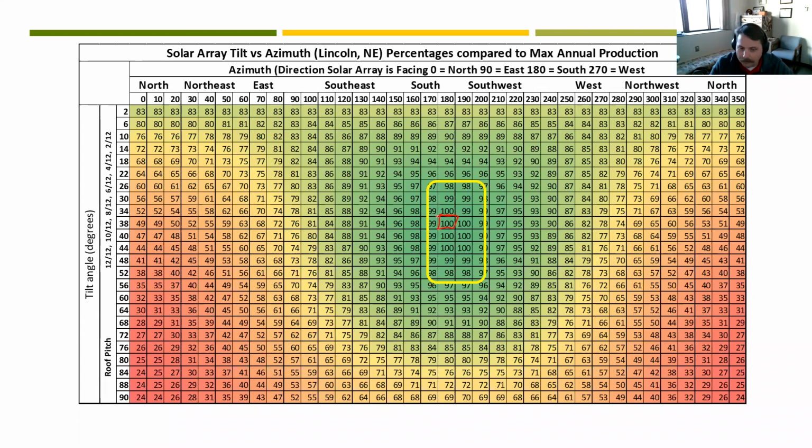And so although that is optimum, if I were to put that at a roof pitch of 4/12, I'm somewhere in here. Yes, I lost 5%, but what did it cost me to save that 5%? It costs money in racking, in wind loading, and things like that. And I'm suggesting it may be worth it just to add another solar panel to regain that total production rather than try to mess with a different rack.